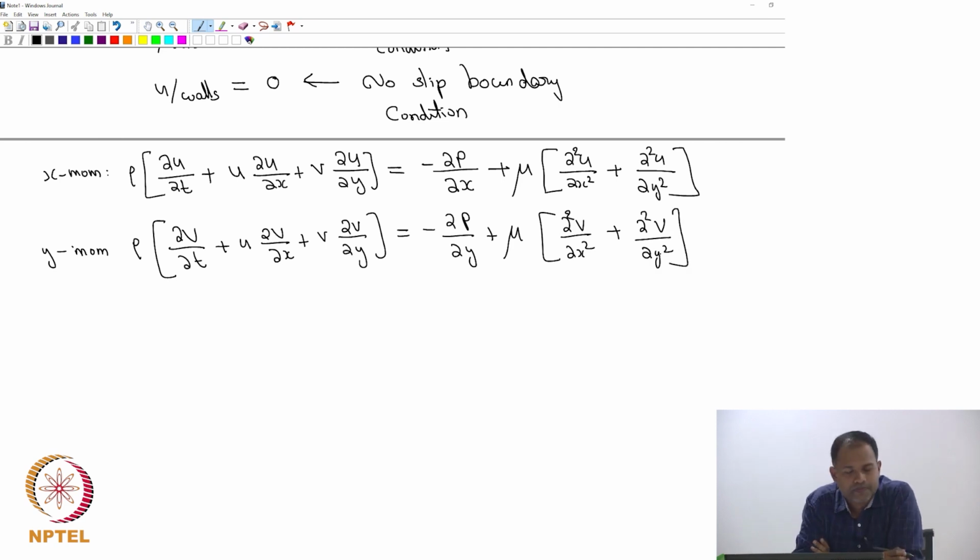All right. So we know that V is 0, so that makes our y momentum equation very simple, almost everything goes away except pressure, because we haven't said anything about the pressure. The reason why we did not say anything about the pressure is because we did not say anything about the force so far, because pressure is nothing but force per unit area, right. So it will come only in a force balance. All our analysis was about continuity equation, that is why pressure never came into the picture so far. Now pressure is coming first time, and it says that dou p by dou y is 0.